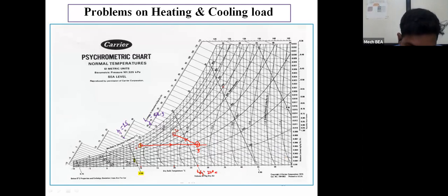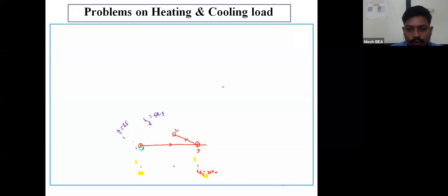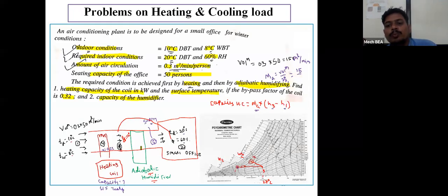This line that you see is 0.80, and this is the line which is indicating the 0.90. So this line is 0.80, this line is 0.90. By judgment, you have to consider the value of specific volume. As this point is nearer to 0.80, this value will be nearly equal to 0.82 or 0.83 or 0.825. You can take anything, so a small difference will be there.